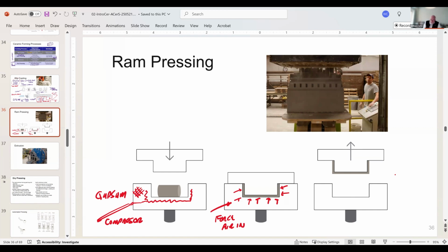They have tubing in here, basically, and at the top they pressurize that. Then they put a board under here and catch the piece when it falls off. Not a big piece like this, but that's essentially how they do it. If they're making dinnerware, large casseroles or whatever, they keep it on the top mold and then release it to the bottom. This picture is okay, but in fact, you'd rather see the picture look more like this with the draft angle here rather than a straight wall, because a straight wall doesn't work.